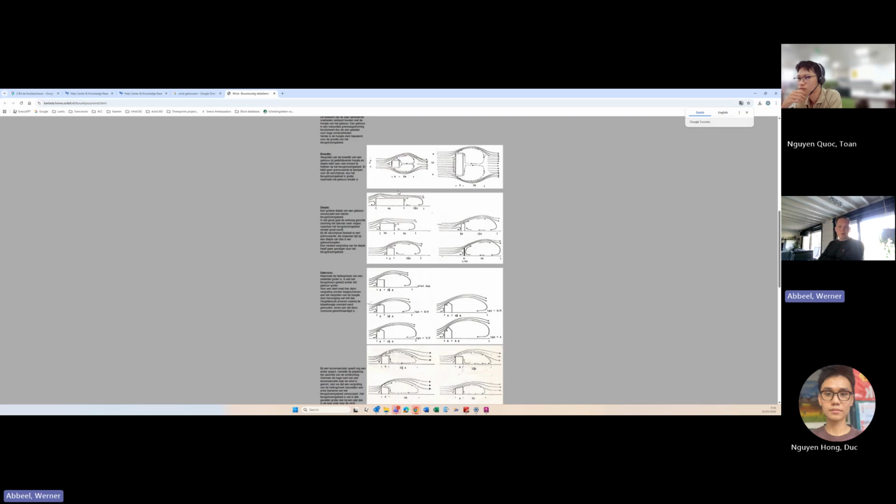Also after a while you know that the closer you get to the edges, the more ballast you need. And then some smart people said, but if you cut off the panels with a lot of ballast on the edges, then we need less ballast. No, because then the other panel will be a side panel and will need more ballast. So it's not working like that. It will increase because you get farther away from the roof edges, but in theory, it will not work like that.